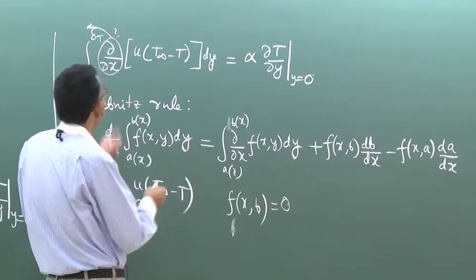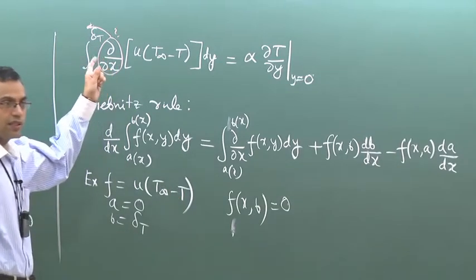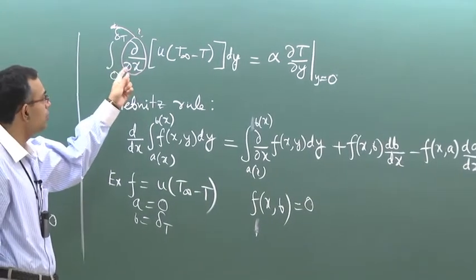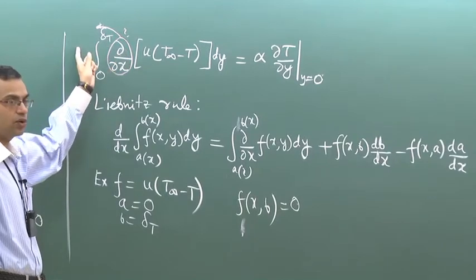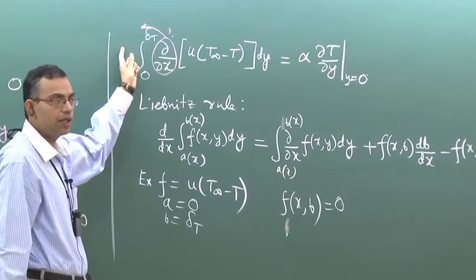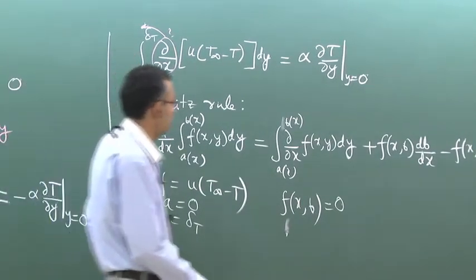So that means here also, just like what we could do for the momentum equation, we can take this derivative out of the integral without any problem because the correction terms are 0.